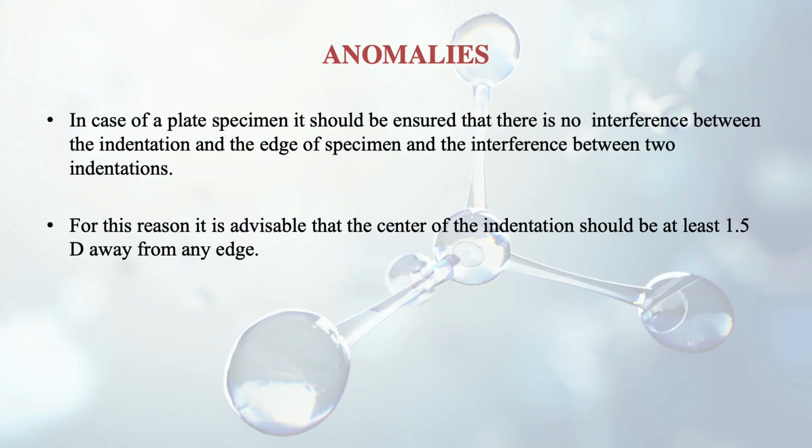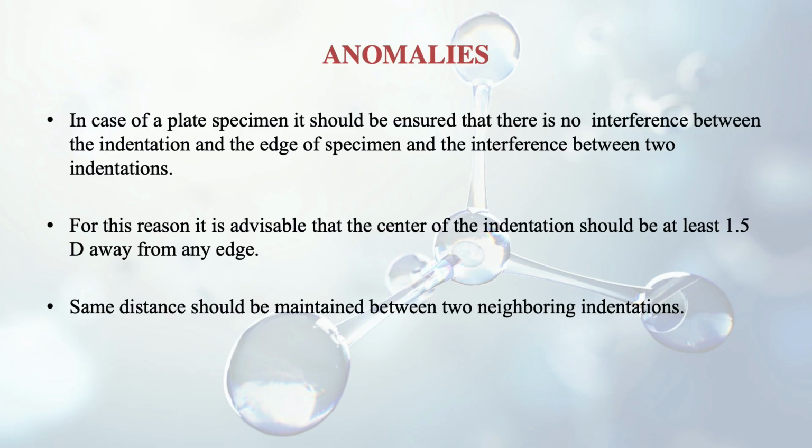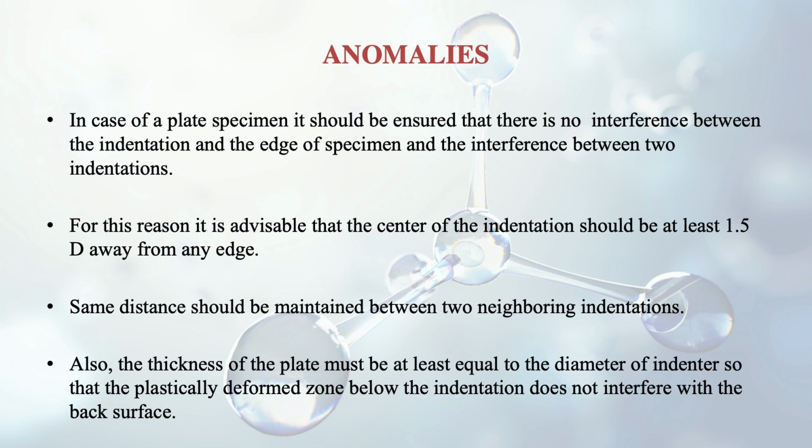For this reason, it is advisable that the center of indentation should be at least 1.5 times capital D away from any edge. So that is a standard distance from the edge of the specimen. The same distance should be maintained between two neighboring indentations, at least 1.5 times capital D. Also, the thickness of the plate must be at least equal to the diameter of the indenter so that the plastically deformed zone below the indentation does not interfere with the back surface.